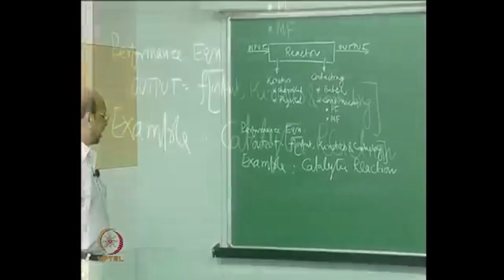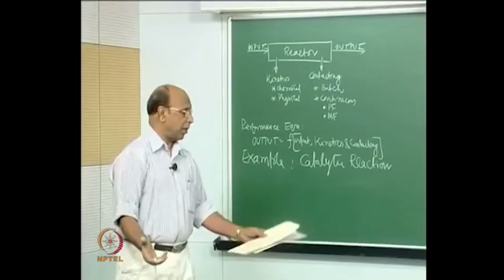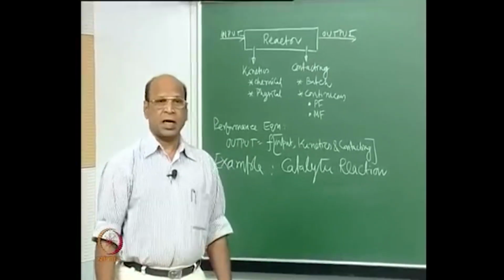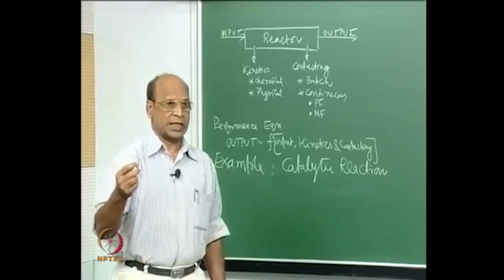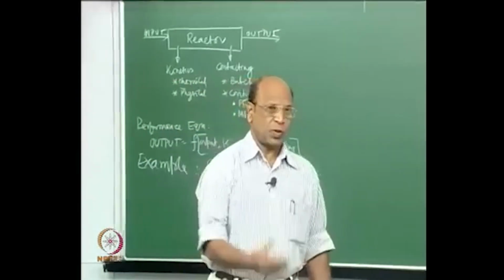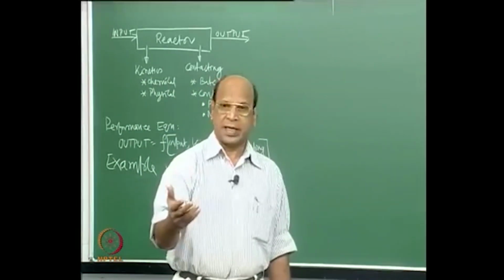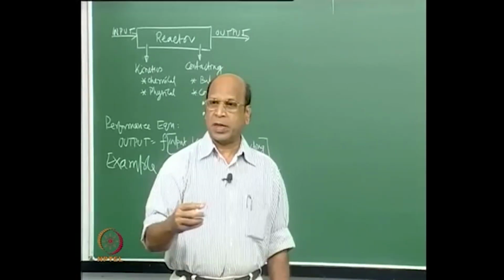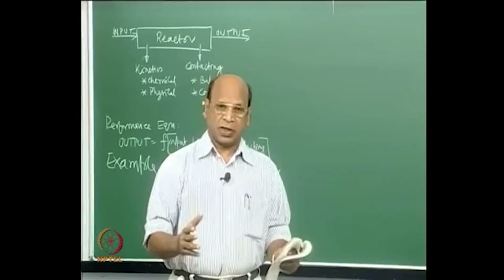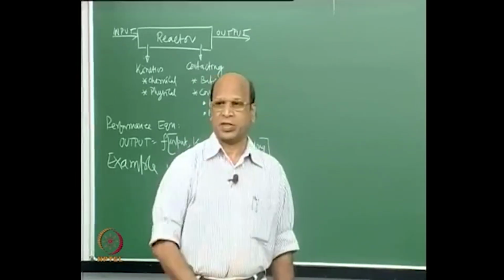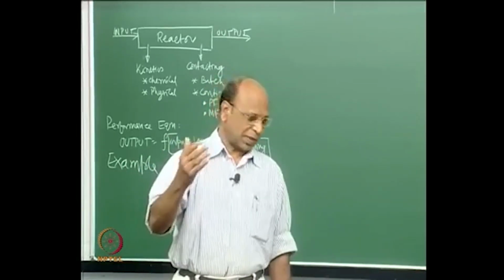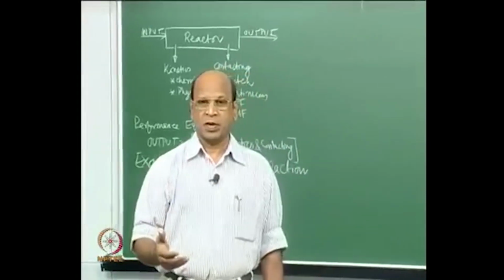This catalytic reaction may be taking place in a packed bed reactor, or in a fluidized bed reactor, or even in a moving bed reactor. In FCC, fluid catalytic cracking, they use one system, and you may say it is fluid catalytic cracking or fluidized bed catalytic cracking, but that fluidized bed is not the classical fluidized bed. Classical fluidized bed has the solids in the form of a batch, whereas in the FCC it is a moving bed, or in other words sometimes we also call it a fast fluidized bed.